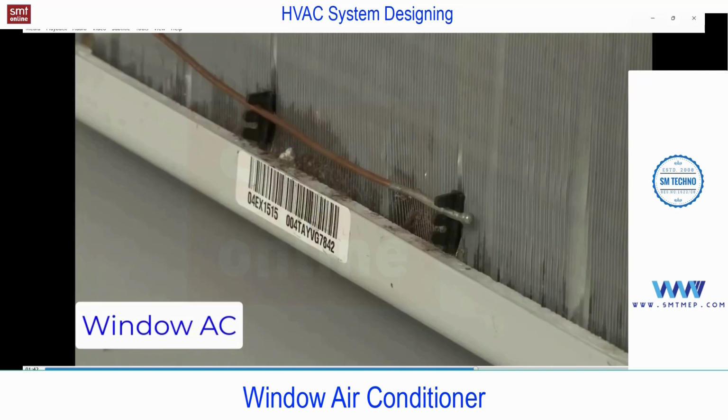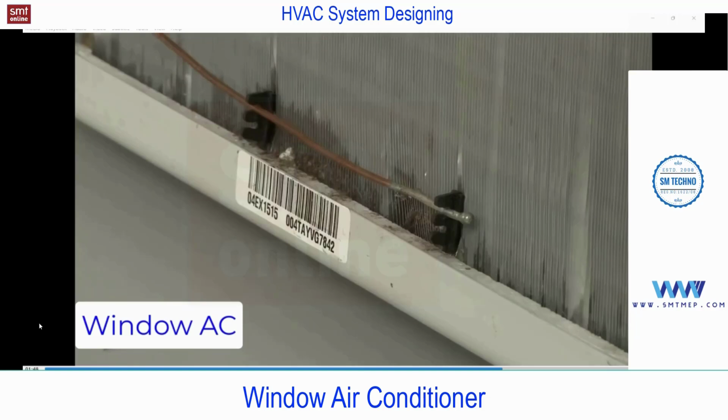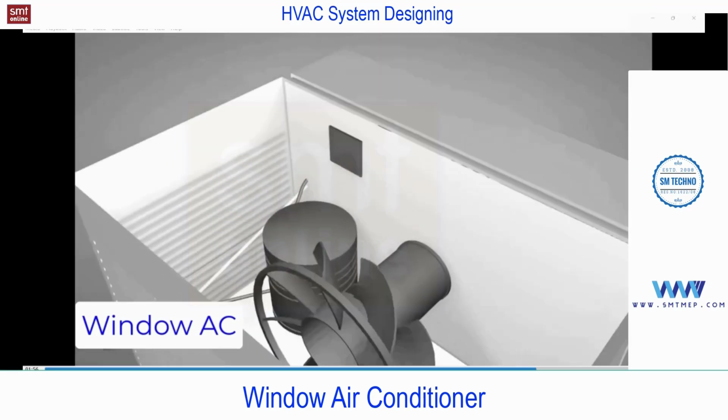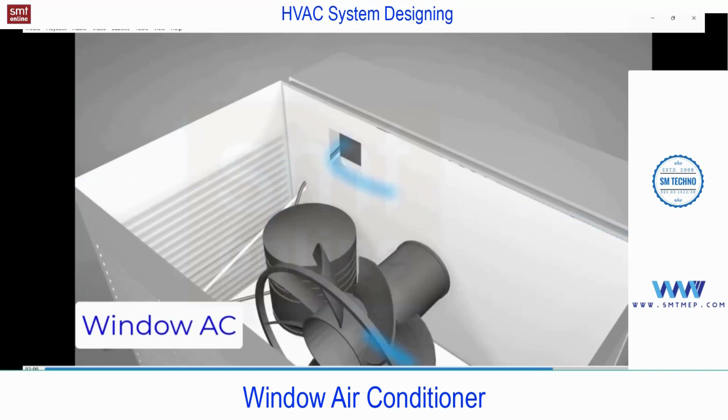Next, the sensing bulb is clipped to the front of the evaporator coils to monitor the temperature of the air entering the coils. Once the room has sufficiently cooled, the thermostat control shuts off the voltage to the compressor. Some models which use a vent can operate the fan motor. You see, this is a fresher option in some models, not in all the models, in window, only to draw in cool air at night.